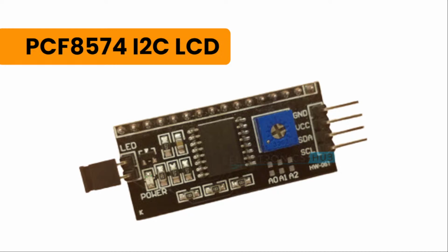There are many display devices like the OLED display, 128x64 graphical display, and the Nokia 5110 display. But for displaying a simple text and a number, all we need is a 16x2 or 20x4 character display. The main disadvantage of that display is it requires a lot of wires, a lot of GPIO pins of a microcontroller to function properly, right? This is not even the 8-bit mode but reduced to 4-bit mode. Think about the 8-bit mode.